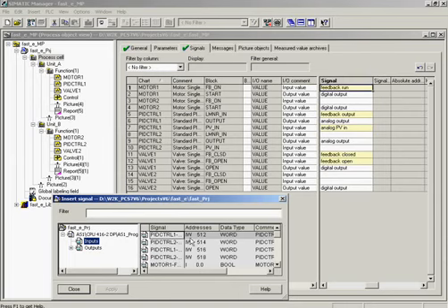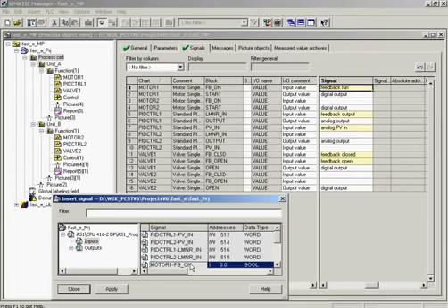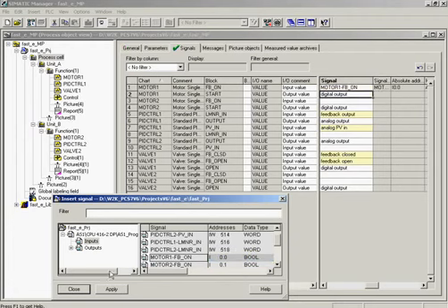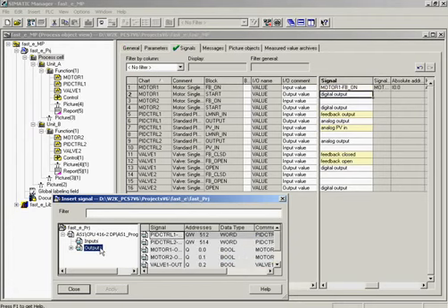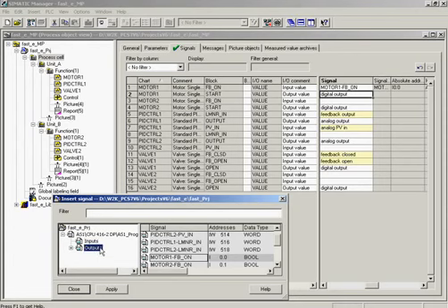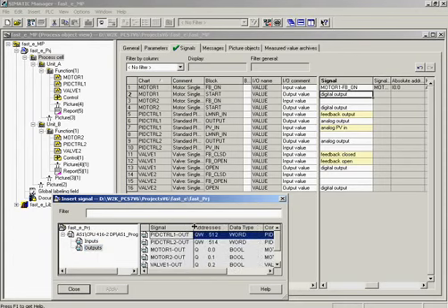The signal names contain the name of the measuring point, the chart column, and the name of the channel drivers in the module column. The signal that is to be inserted is motor 1 FB on. It is selected and will be applied by clicking the Apply button. The other signals are connected in the same manner. For the Start-Stop command signal of motor 1.